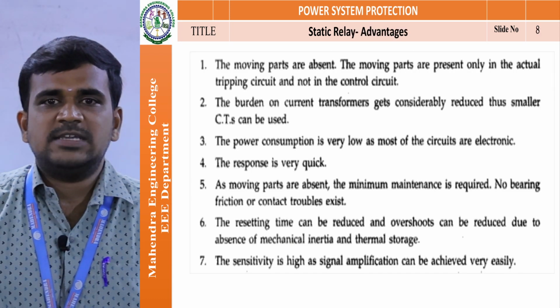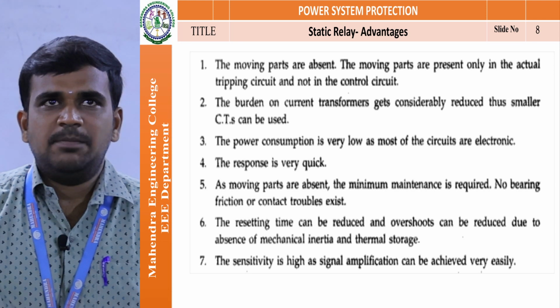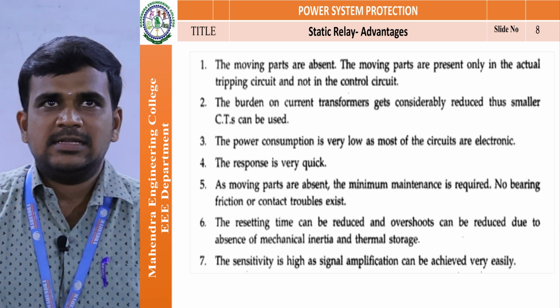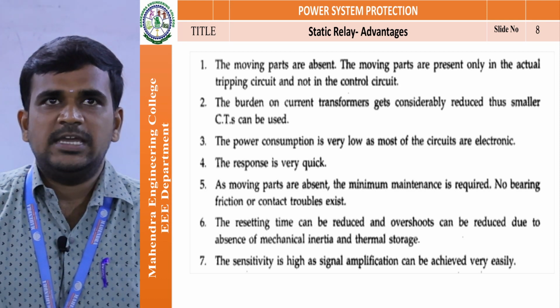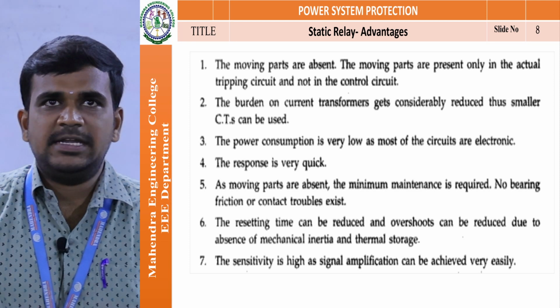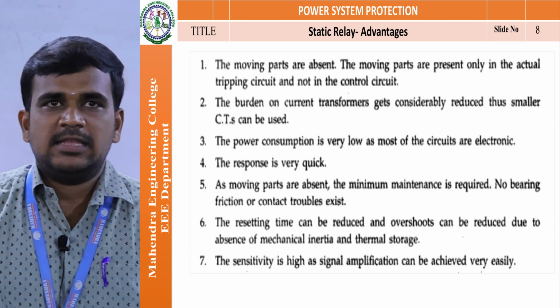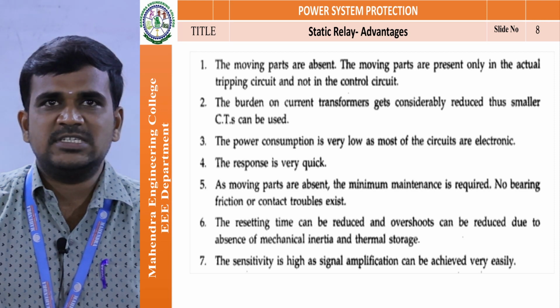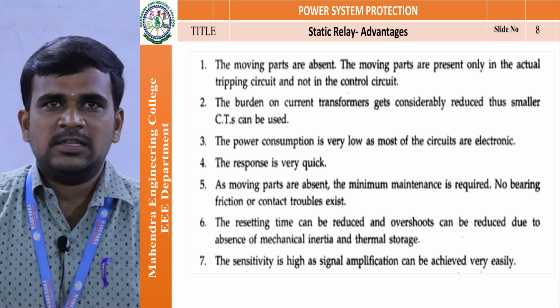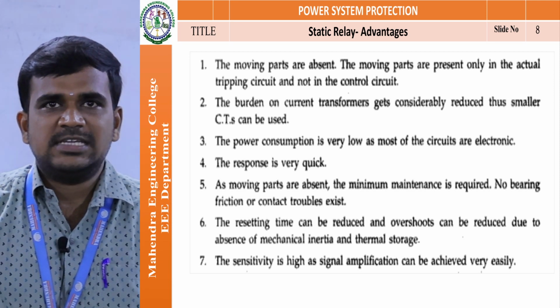The major advantages of static relay are given below. Number one, the main advantage is no moving parts. So power loss consumption is very low, and also only CT and PT are used, so no losses. And the fourth one is that the static relay response is very quick compared to the electromagnetic relay. Then the fifth one, no bearing friction or contact troubles exist.